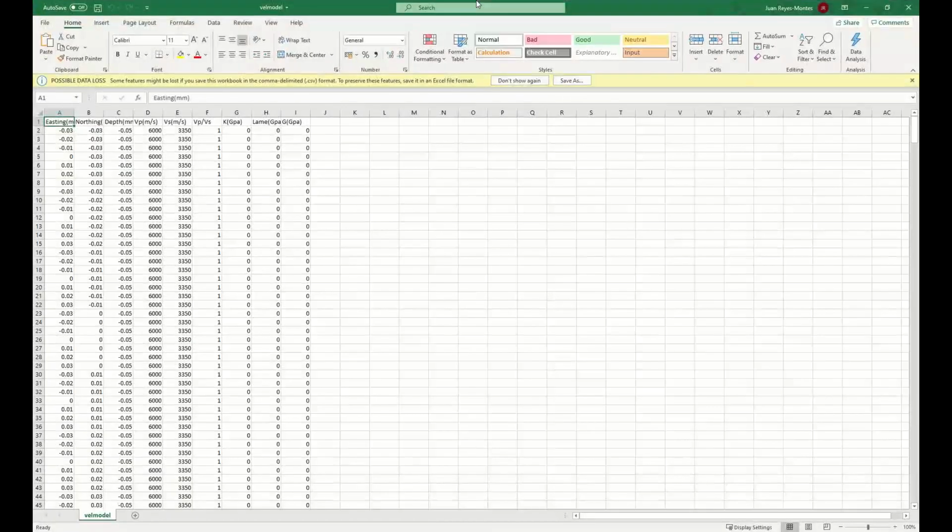It's just basically a text file where you can introduce the center of your boxes. So we have voxelized our space, our rock sample. In this case, we're working on 1 by 1 centimeter cubes. We divide our sample in cubes of 1 by 1 centimeters, and we can define for each of those cubes what would be our VP velocity and our VS velocity.